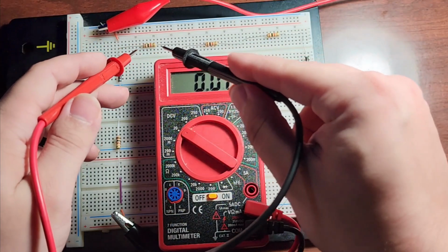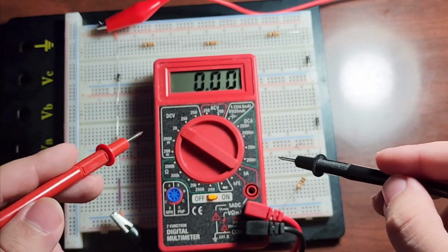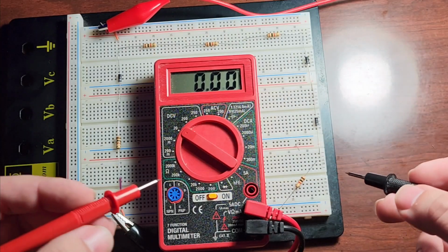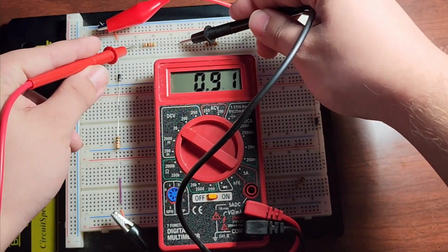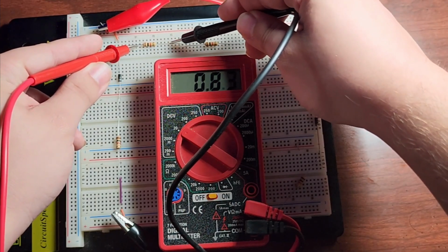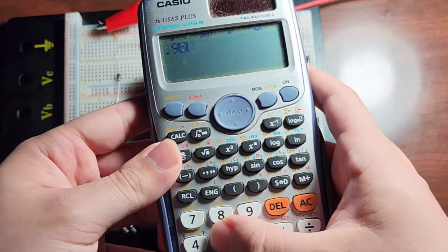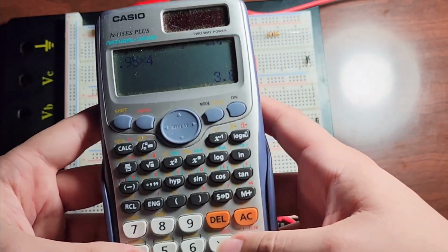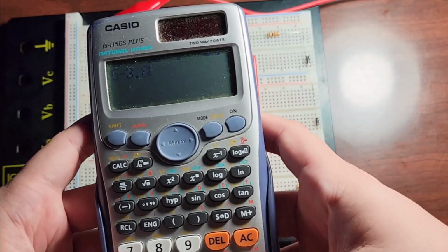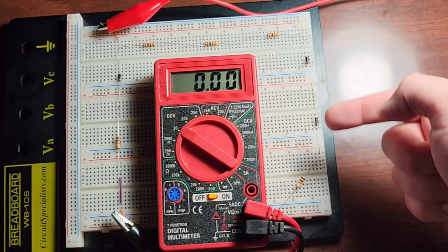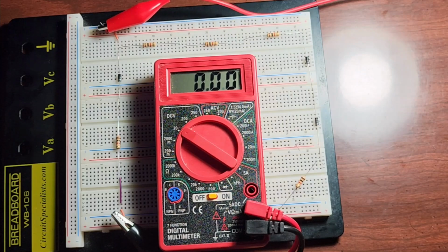And so what you'll see is 1 volt plus 1 volt plus 1 volt plus 1 volt, that's 4 volts. That means this should be about, I guess, half a volt. I guess if it's 0.95 though, you should really take that into account, right? So 0.95 times 4 is 3.8. Then you have 5 minus 3.8, it's about 1.2. Which is, you know, we had 0.6 and 0.6, that adds up to 1.2. So that's what's happening. This is a very simple diode circuit that you would see on an exam.